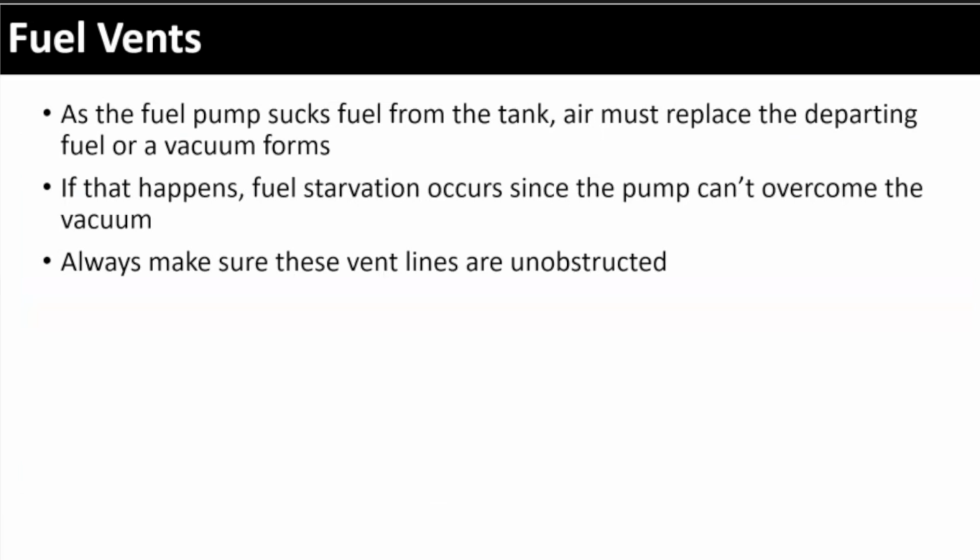So what makes sense? You need to have a way to vent to allow air to replace that space, take up that volume in the tank as that fuel is being consumed, right? So we want to make sure those vents are open, because if those vents are not open, we continue to cause a vacuum in that tank. What's eventually going to happen as you're at 5,000 feet in the air? You're going to find the engine's not getting any fuel, right? You're going to get starvation.